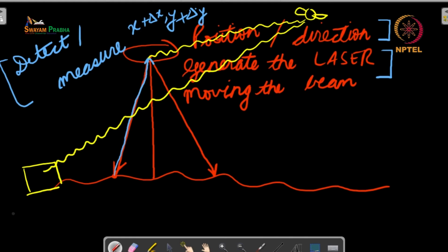Similarly at the ground station you have the coordinates given by alpha and beta, but here again because the signal has an error, you have alpha plus delta x and beta plus delta y. This is because the error is the same, since it is coming from the same satellite, and in that case you can now compute the location of the aircraft with respect to the ground station,